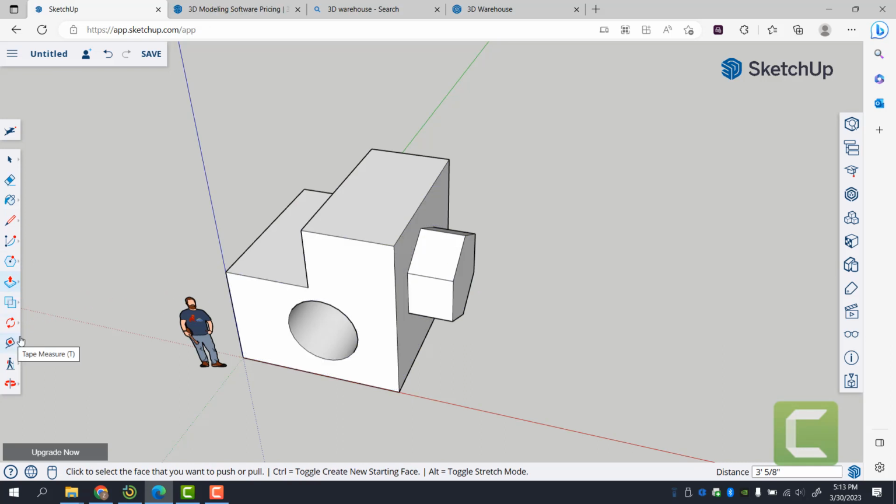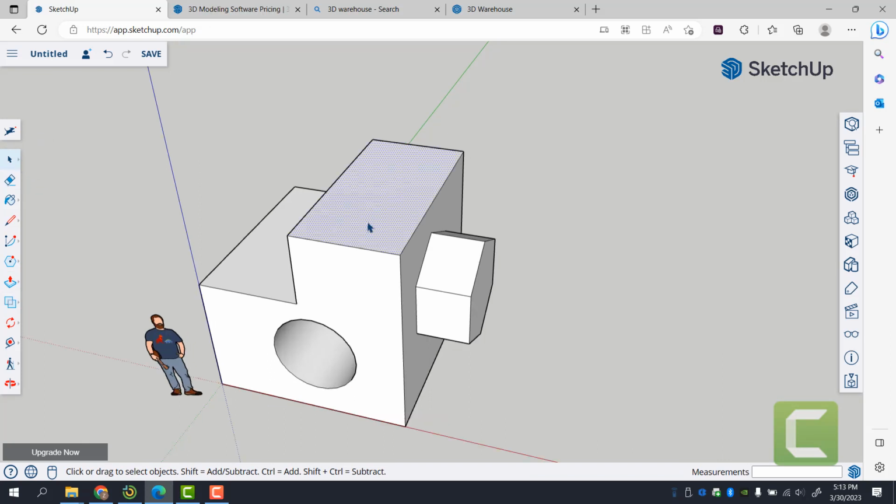So if you want to isolate multiple objects, you can triple click. So this is another feature in SketchUp that is unique to itself. If you single click on an object, it selects the surface. Double click on that object, it selects the surface and its edges.